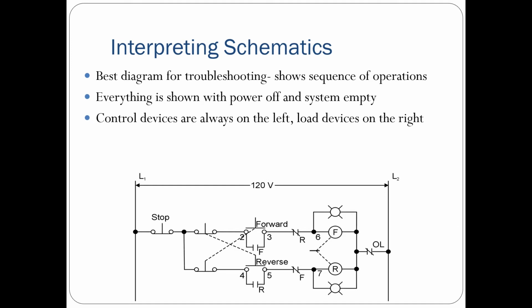When I'm arranging my devices inside my schematic, I always want to follow the same pattern. I want to have my control devices on the left and my load devices on the right. This makes it easier for me to design my schematics and it makes it easier for other people to read them.